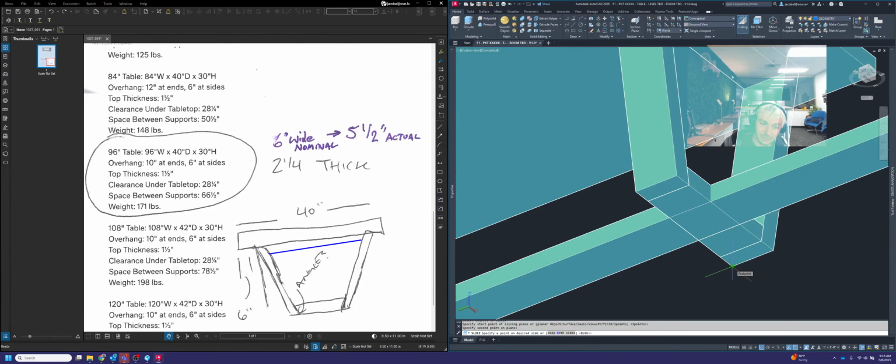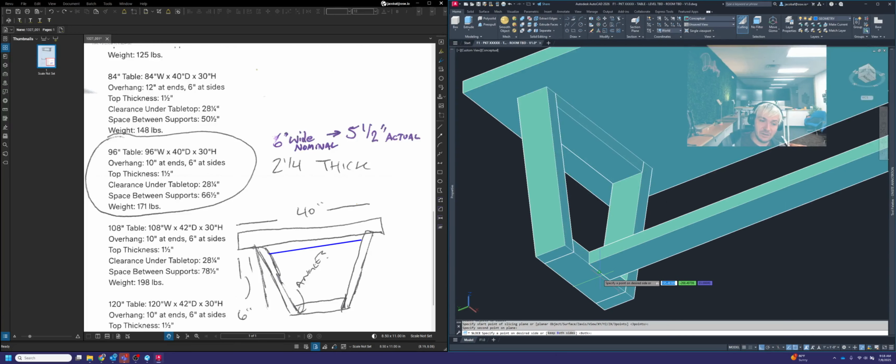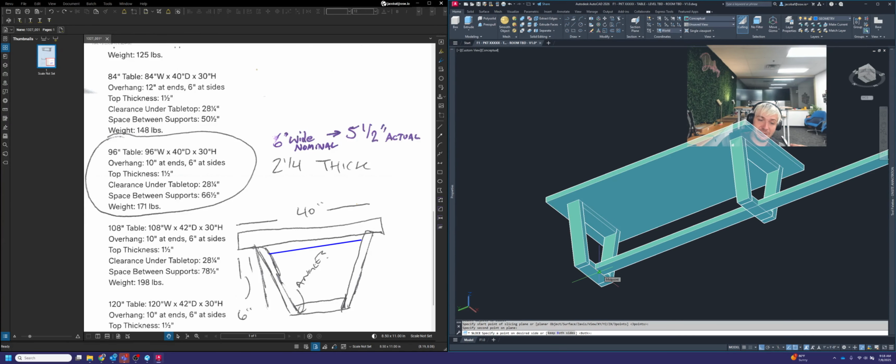And then it's going to ask me what side do you want to keep. If you'd like, at least when you're new, it might be beneficial to keep both sides. If you are more comfortable with AutoCAD and you're okay with picking a side without goofing anything up, then you can just click on the side that you want to keep. So here, what I'm going to do is click on this point here, and it will only keep this side, and it will erase anything past those 2 points that I selected.